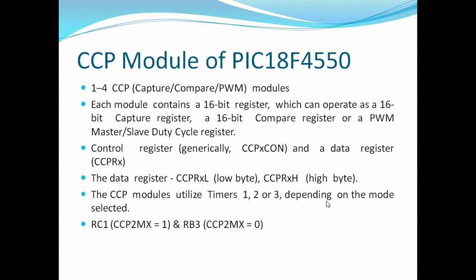So two CCP modules are available for programming by the user, in which the user can program the microcontroller for capturing events, comparing two values, or generating pulse width modulated output for driving a DC motor or for driving LED displays.